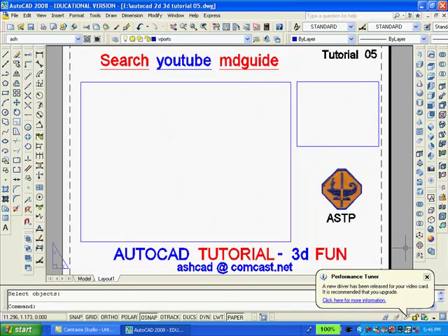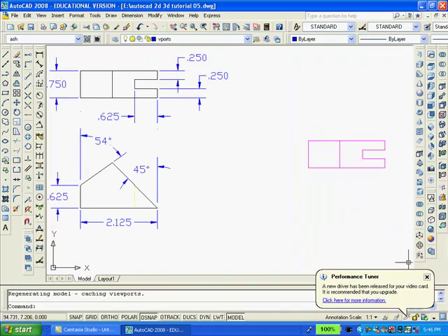You can see that the drawings have disappeared from Paperspace. All that remains are two rectangles which I drew previously to serve as templates for when I redraw the viewports later on. To get back into Model Space, I will now click the Model button. With that accomplished, notice that both drawings still exist in Model Space even though they were erased in Paperspace. Now I will erase both drawings from Model Space so that I'll have room to redraw both the 2D and solid.